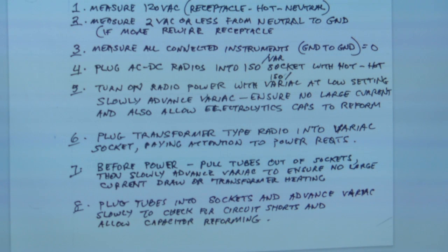And it's called an intermittent dynamic short. And it's a real headache. Some transformers, of course, will short at a certain voltage anyway, and you have to know that, because you have to know whether you have to replace a very expensive item like a transformer or not. It might make the whole radio not even worth working on.